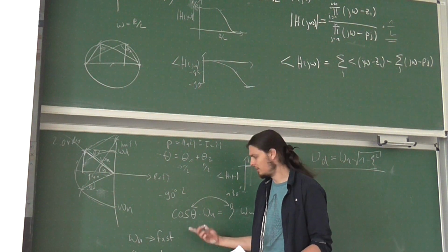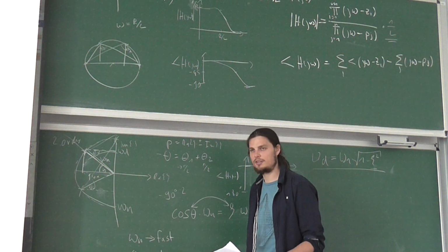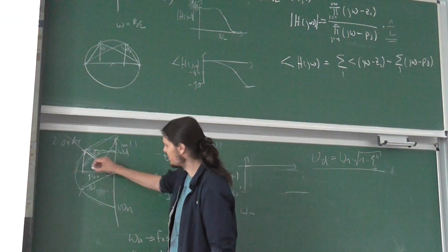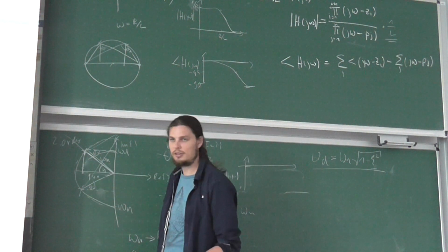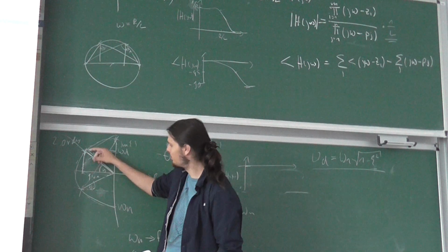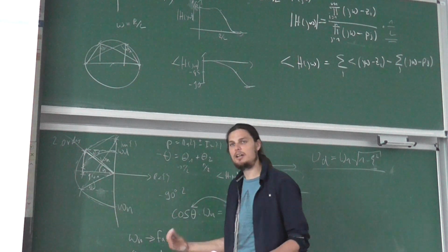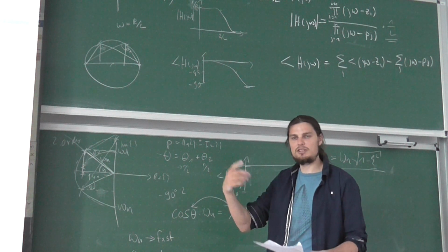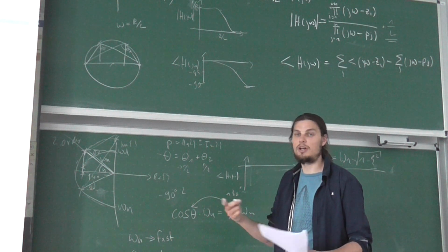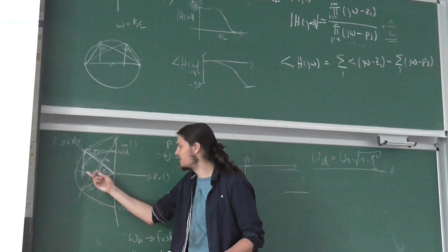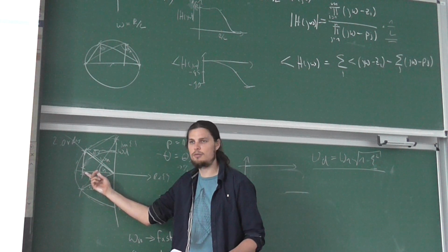What's the damping, and how fast are they? Is it a good idea to put these poles here? They're fast and damped. If I put them down here, if I know I have the system, maybe, and you will see in root locus, I can basically sometimes choose where they are, or that's what we try to do. Is it a good idea to put them really close to the real axis?